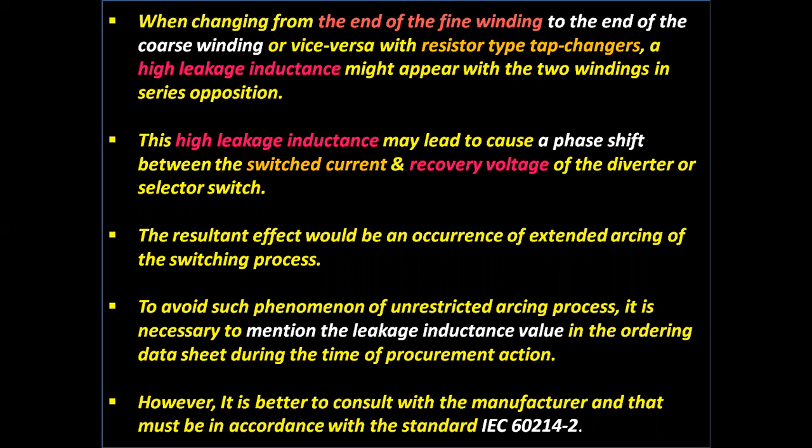This high leakage inductance may cause a phase shift between the switched current and recovery voltage of the diverter or selector switch. The resultant effect would be an occurrence of extended arcing of the switching process.